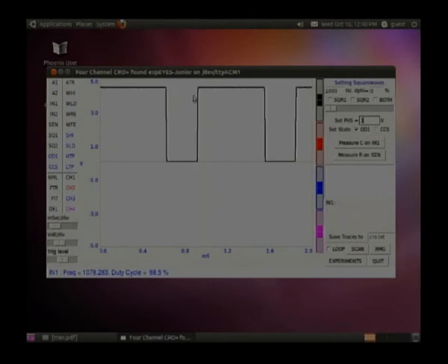And if you really want to do that by giving some commands, it is possible to enter that in this window. If I type R to F time 3,3, that 3 actually means the input IN1. If you see on the box, the number 3 will be marked, that is the channel number of IN1, and it says that the time from rising edge to falling edge is 638 microseconds. Similarly, you can measure the rising edge to rising edge, and from these parameters you can calculate the frequency as well as the duty cycle.